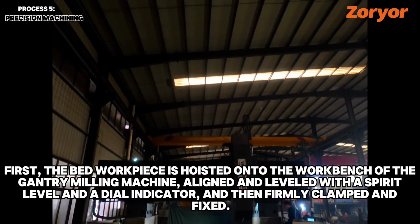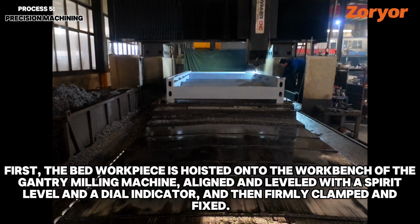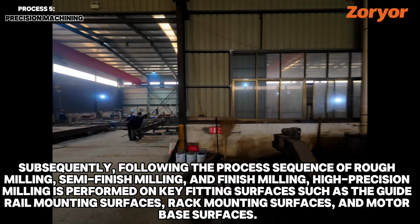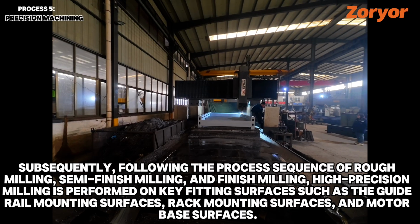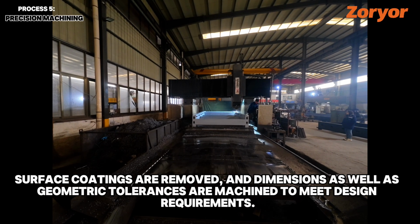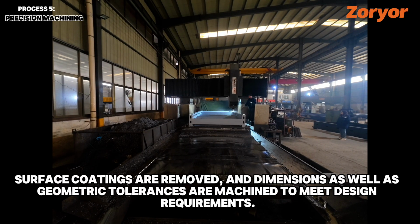First, the bed workpiece is hoisted onto the workbench of the gantry milling machine, aligned and leveled with a spirit level and a dial indicator, and then firmly clamped and fixed. Subsequently, following the process sequence of rough milling, semi-finish milling, and finish milling, high-precision milling is performed on key fitting surfaces such as the guide rail mounting surfaces, rack mounting surfaces, and motor base surfaces. Surface coatings are removed, and dimensions as well as geometric tolerances are machined to meet design requirements.